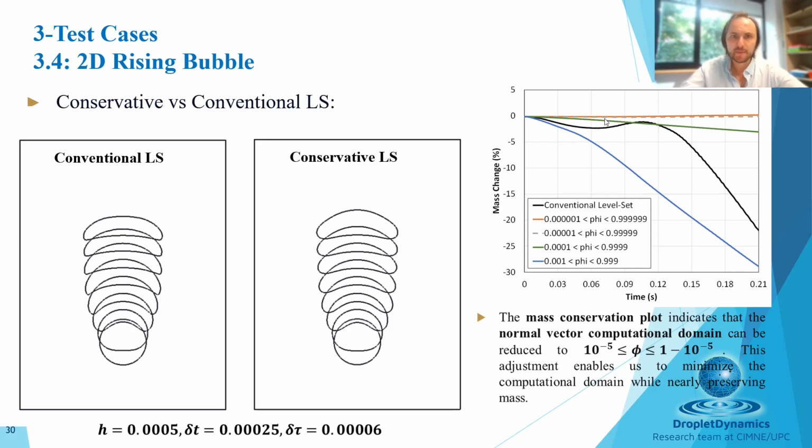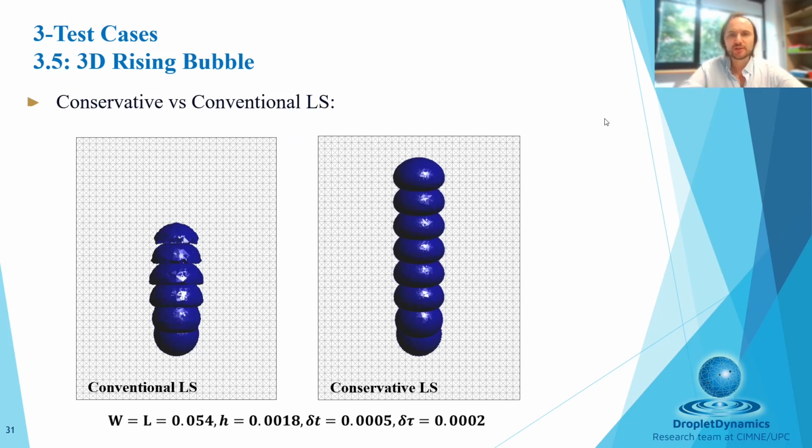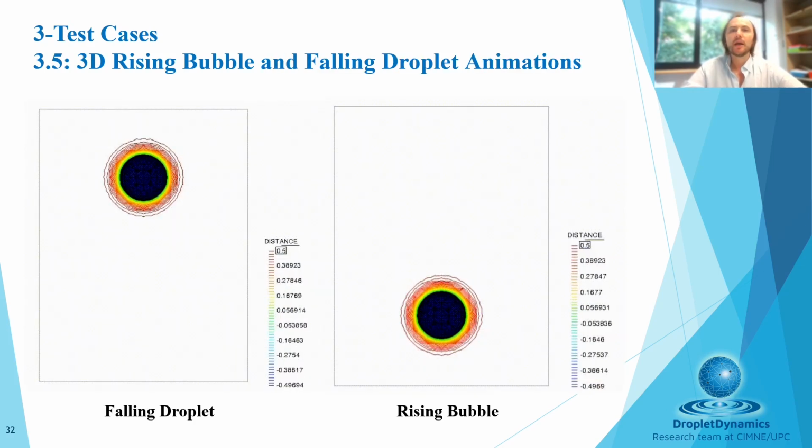This is a three-dimensional example, as you can see, we can obtain very nice results already on such coarse meshes. We don't, as you see, we don't refine anywhere at the interface, and this is thanks to our enriched finite element approach, which does not require any mesh refinement to accurately capture the sharp discontinuity.